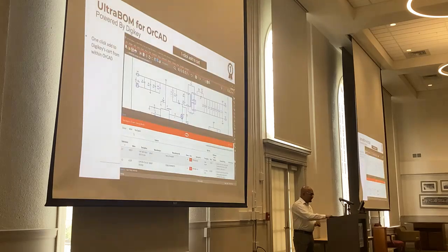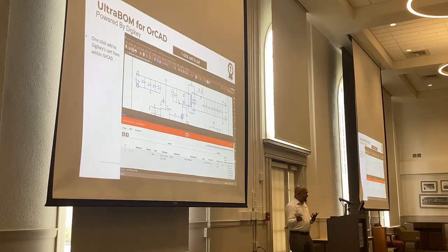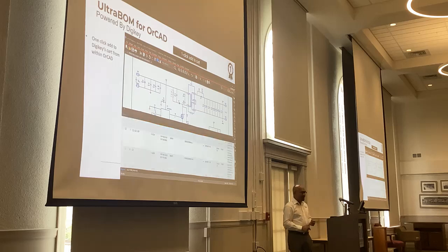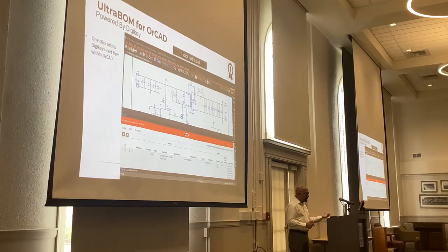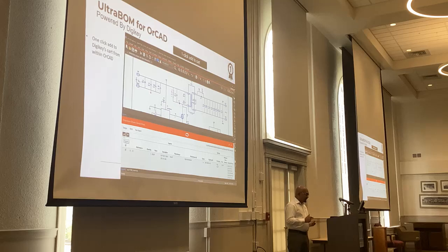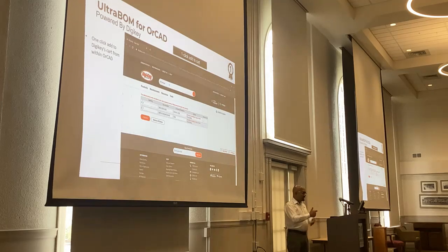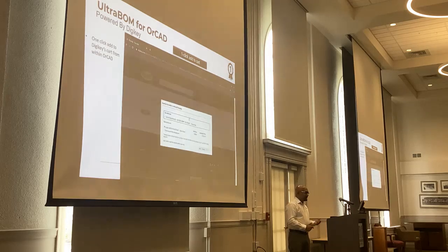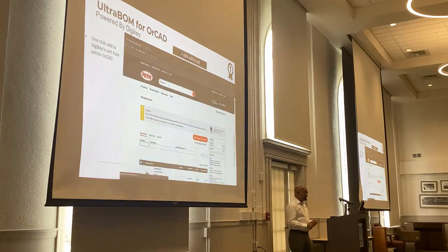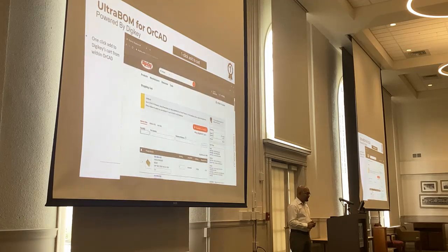And then, the benefit of DigiKey is obviously all the parts on your design now have DigiKey part numbers mapped. You can do a single click, either download the bill of material or send it directly to DigiKey's shopping cart. And obviously, when you send it to DigiKey's cart, if DigiKey finds that one or two parts are not in stock, they'll make some recommendations for alternate parts, and then you can upload it, purchase the entire bill of material.